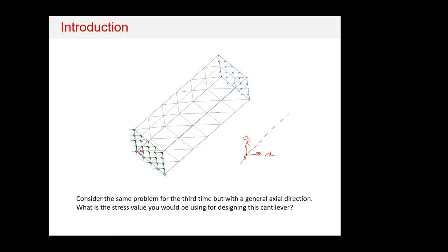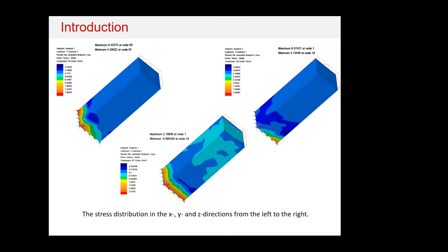Now I'm going to do the stresses again and find out the new numbers for the stress. In this case, I have similar results for sigma x and sigma z, and the numbers I have are 8.5 to 4.2. Now, this is a big difference compared to before. The dominating stress is happening somewhere between 4 point something and 5 point something. So if you look into the majority of the stress here, which is basically the stress you are going to design for, this is around 5. Before it was 10.